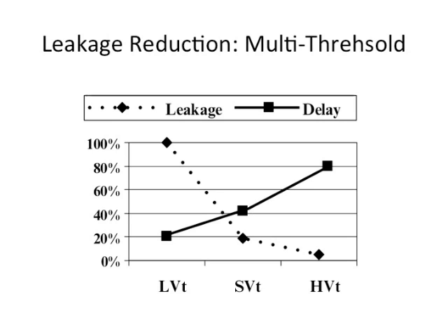Remember the equation for subthreshold current, which is a function of supply voltage and threshold voltage. So by choosing different threshold voltages, if I use a low threshold voltage, then I have more leakage. I have faster transistors because drive current is proportional to V minus Vt, the overdrive. Supply voltage minus the threshold voltage. If I reduce threshold voltage, I have more drive current. Things are faster but also more leaky.